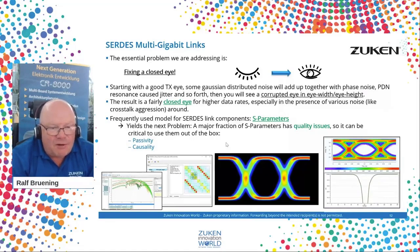This points to the next problem. Experience shows that a major fraction of the S parameters has issues with passivity or causality. So you have to have a process to validate, to check the quality of S parameters.